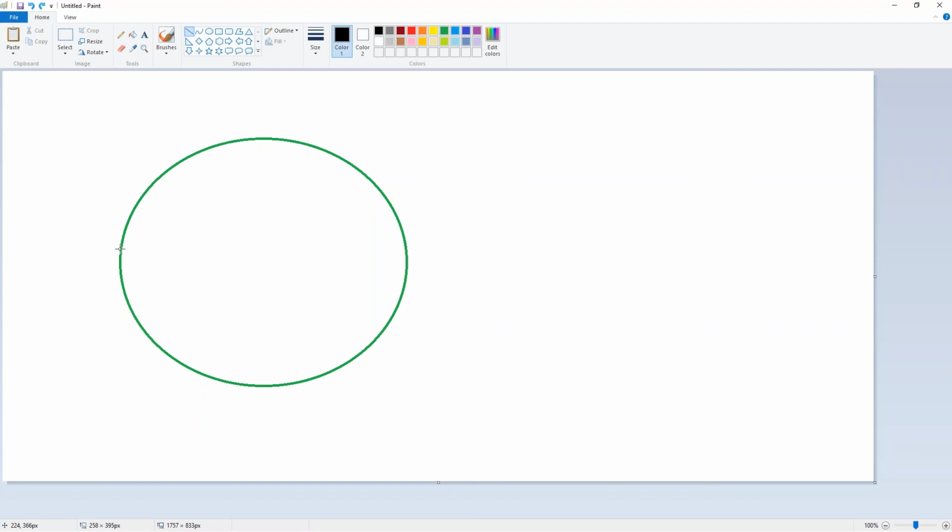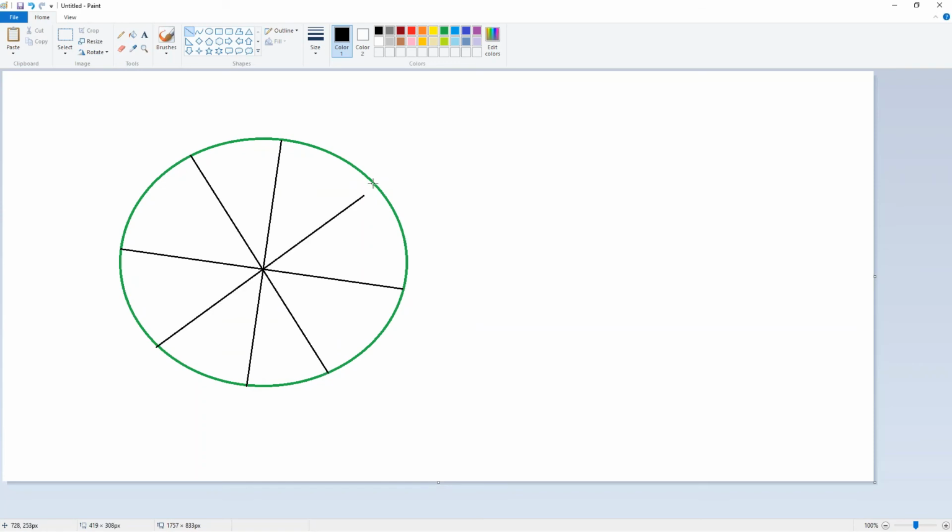You can just do it like that, which has a much better representation of the surface. And that's the reason why in most cases it makes sense to use tetrahedral meshing, especially when we have a complex geometry.